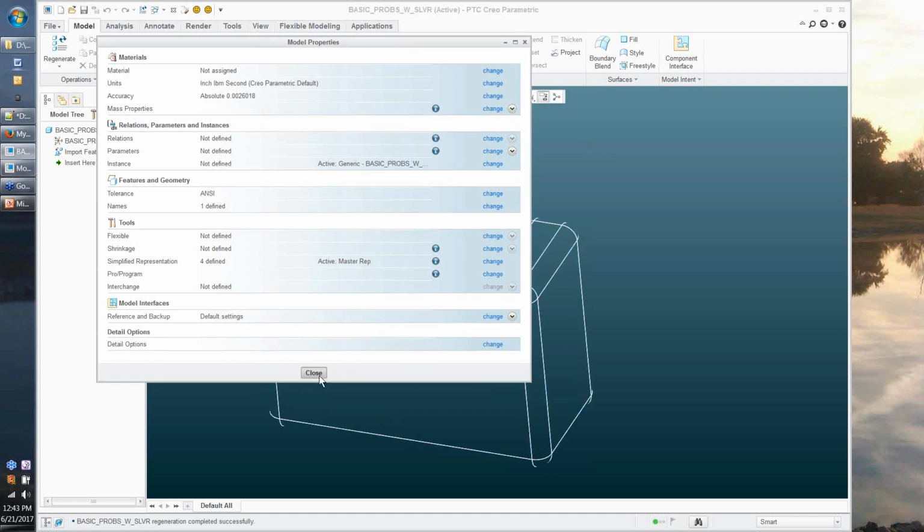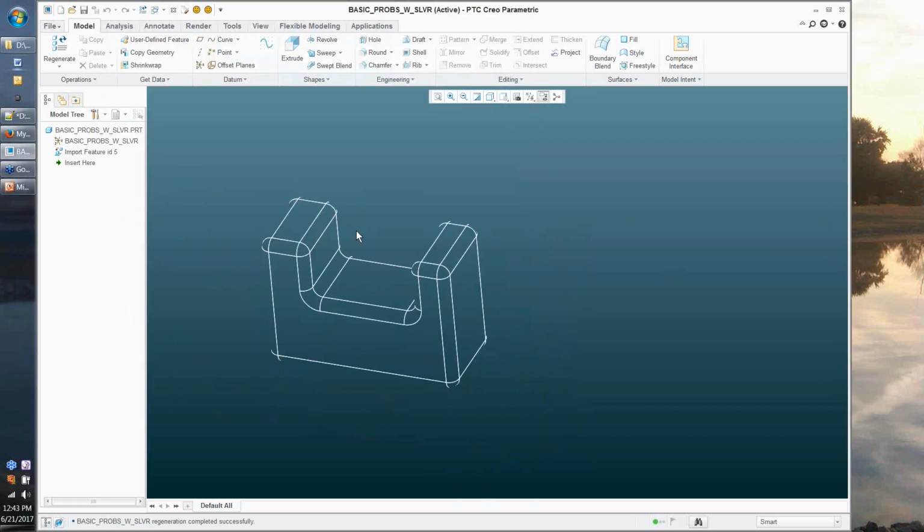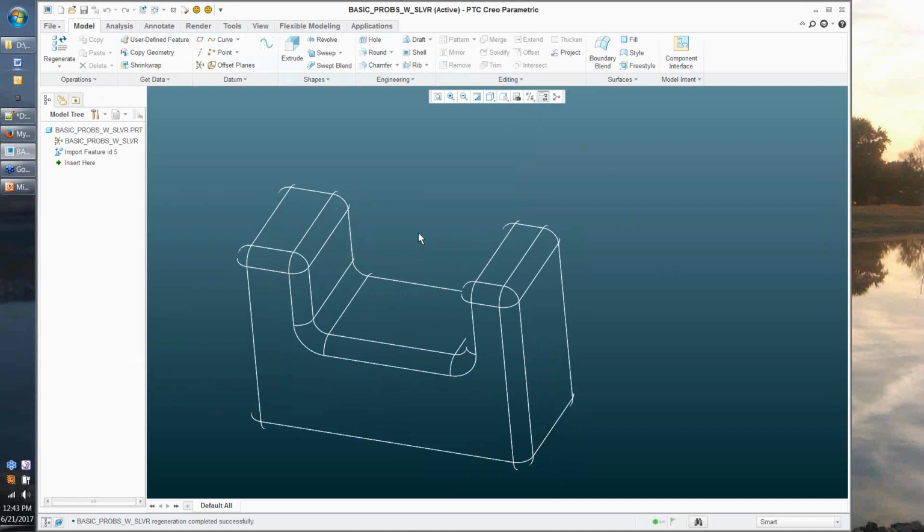Okay. Now, in the context of a multi-cavity mold, where we're dealing with a family mold with dissimilarities or not equal topology, we do have a potentially enormous problem on the face of it. And yes, in that context, the lowest accuracy I can get to is the accuracy I'm going to use, or, I guess it makes more sense to say, the greater of the two part files' accuracy will be used.